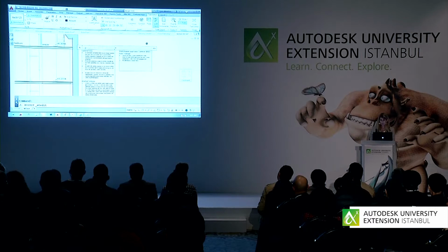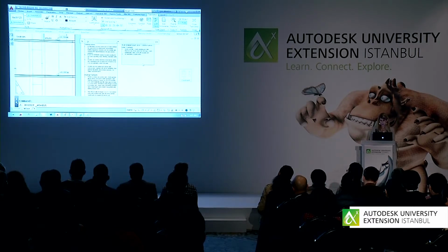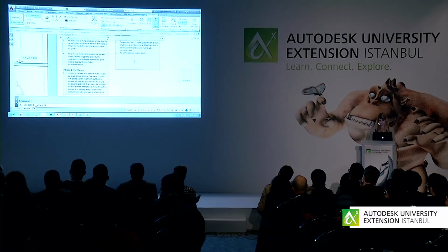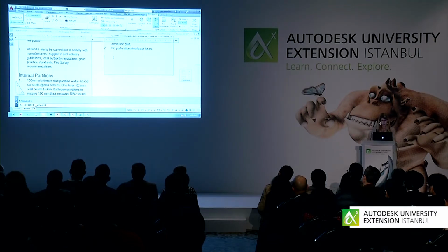M text works a lot more like Word does. You'll see that it's very easy now to change your columns around. Just by grabbing the edge, you can grab the corner, you can grab the bottom. Just much easier to deal with as far as columns are concerned. You will see that it's also easier to work with numbers. In fact, if you do anything that looks like you want numbered items like that, I type that in. As soon as I hit the space bar, it will assume that it is going to be a numbered list, etc.